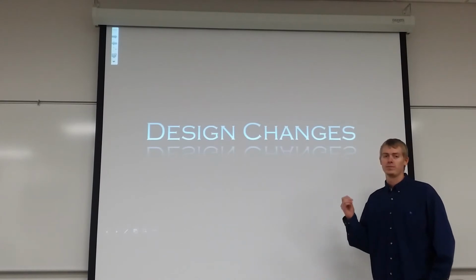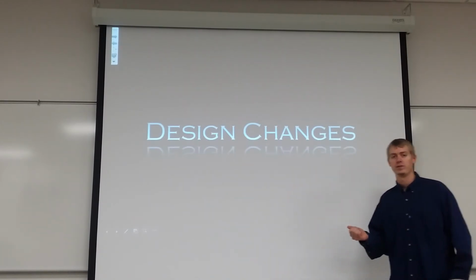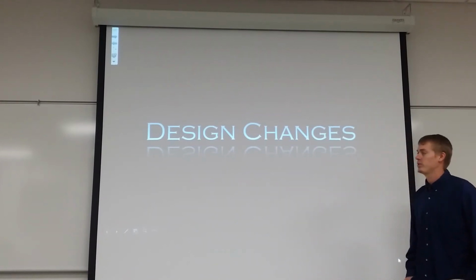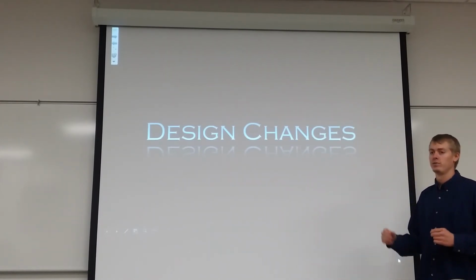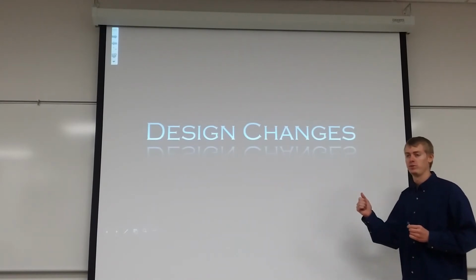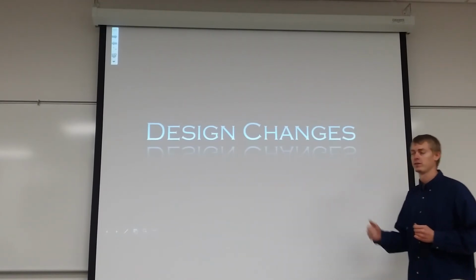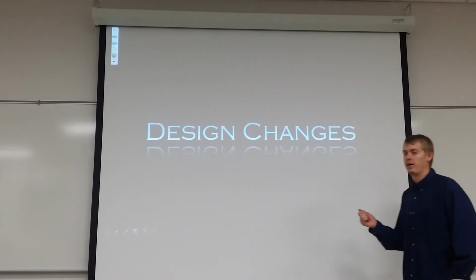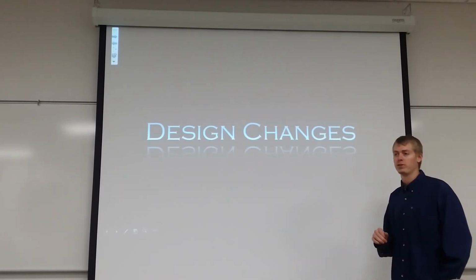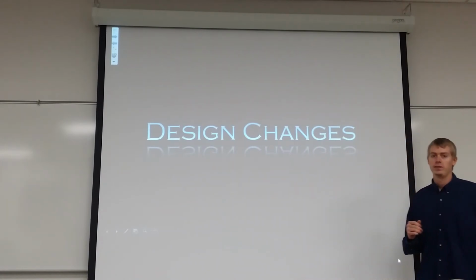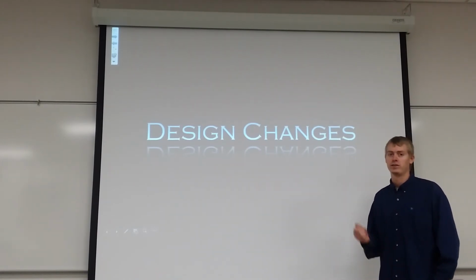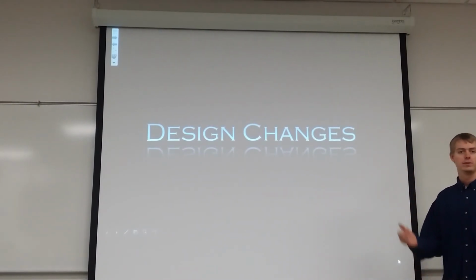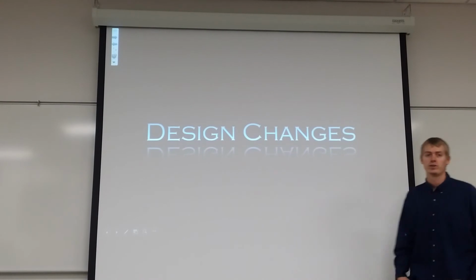In order to keep using this MOSFET, we decided to use what's called a bootstrap circuit. The bootstrap circuit is basically a capacitor and a diode, which is going to keep the gate voltage high enough when the MOSFET wants to turn on. We did use ICs that were specifically made for this purpose, and they still did not fulfill our goal. We had a lot of problems with that. So now we will go on to the actual circuit.